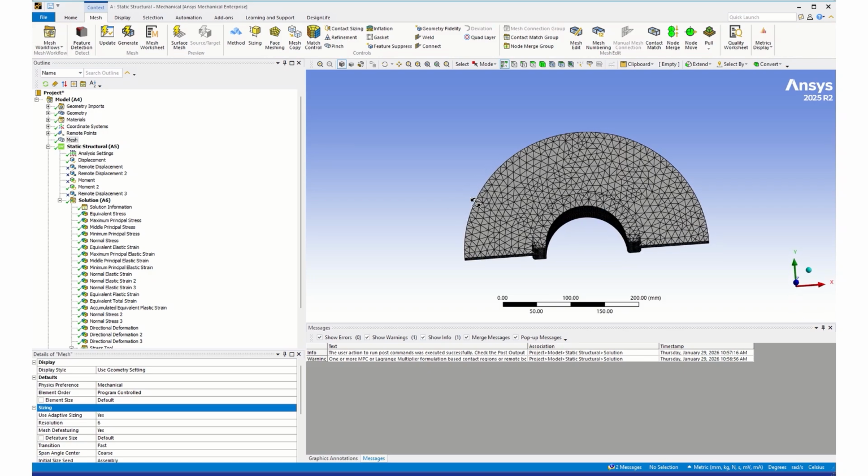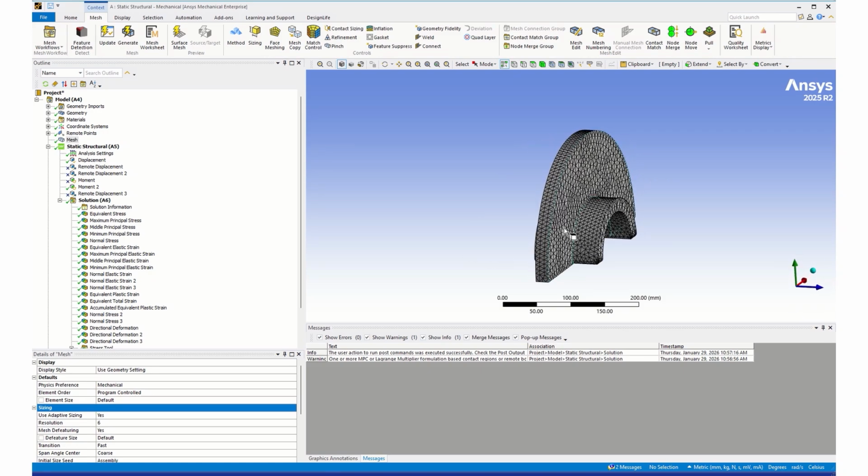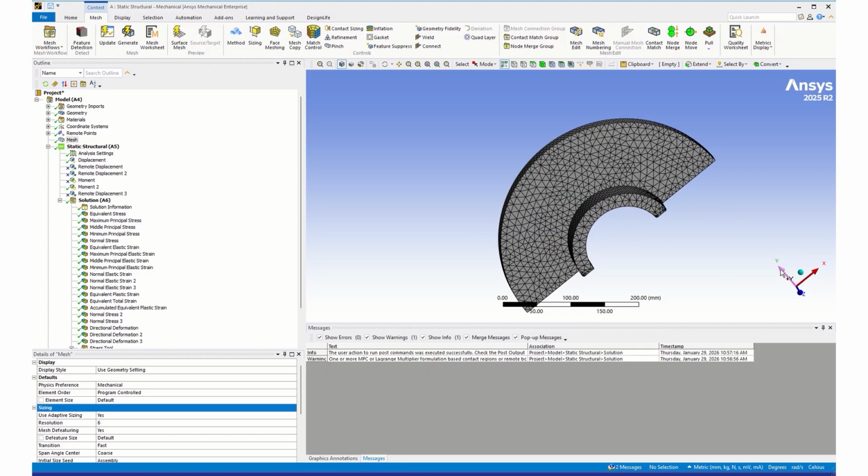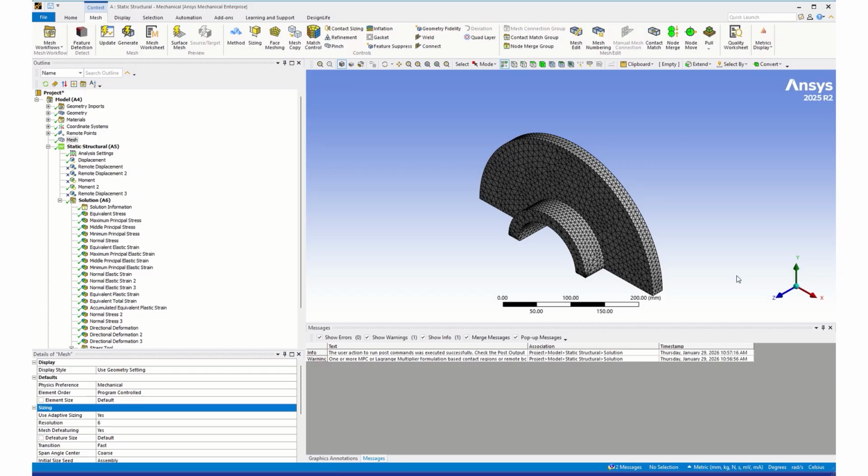Now we're going to load this into the plastic region, so we want to make sure that we have at least 3 elements going across the width. This would be better if we even had more elements. So if I was doing this problem not as a tutorial and needed really good results, I would use a finer mesh than this where I'm going fully plastic. For now, this is the mesh that I will use. So you can just go ahead and mesh it.